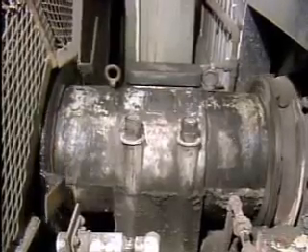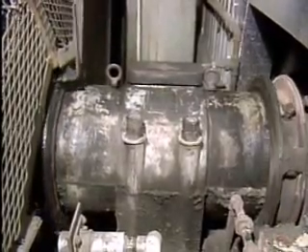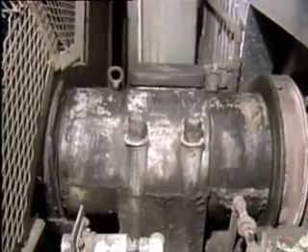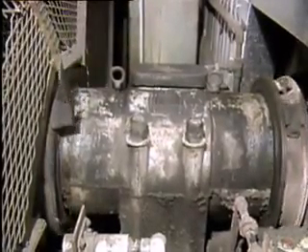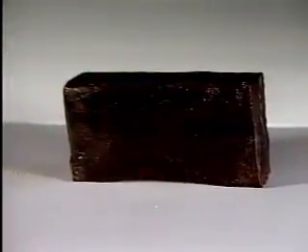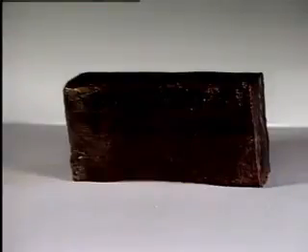This shaft, for example, turns a device that rotates through the hot gases produced in a boiler. The hot shaft turns in a sleeve bearing in this housing. The shaft and the bearing must be lubricated with a grease that will stay in place under high temperatures, like this hard grade 6 grease.